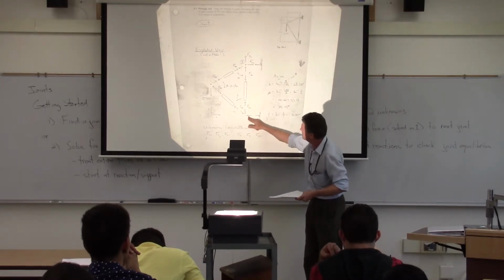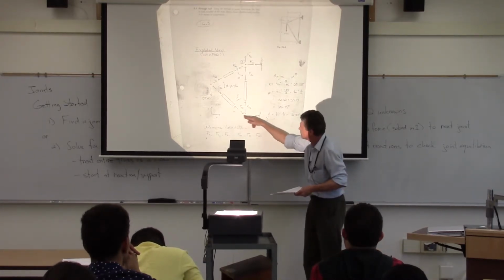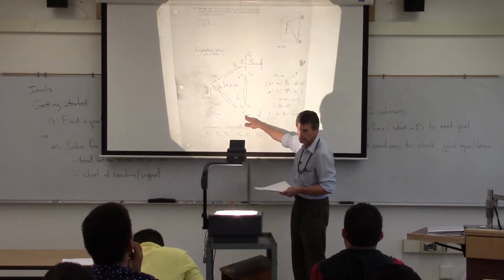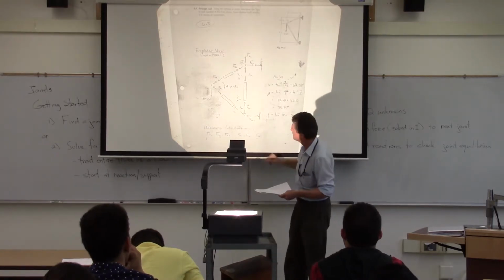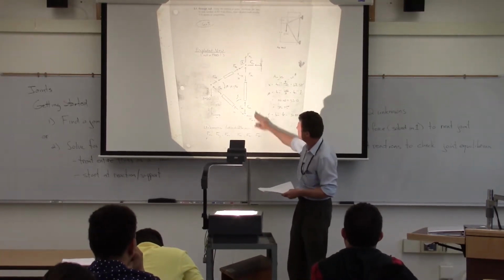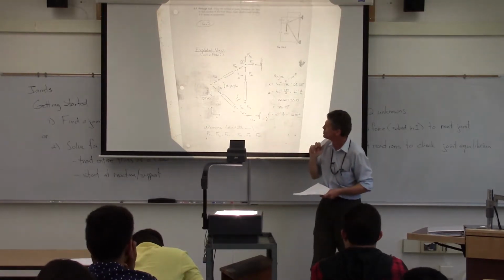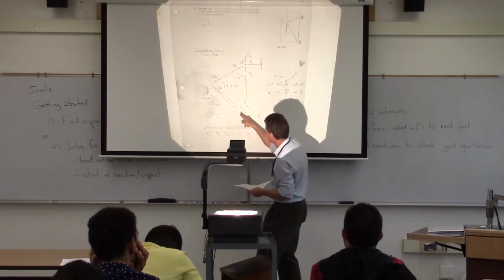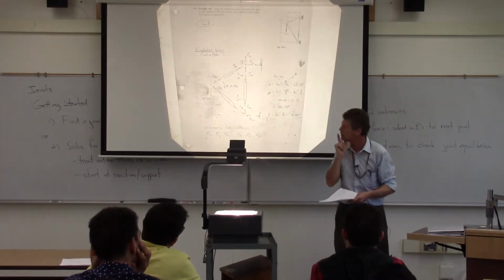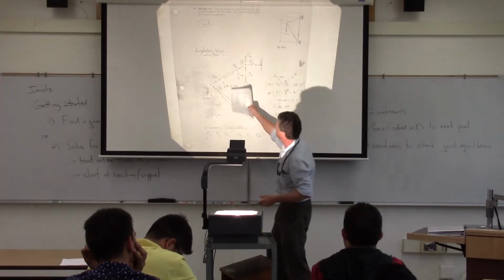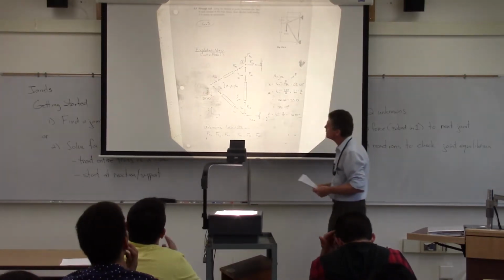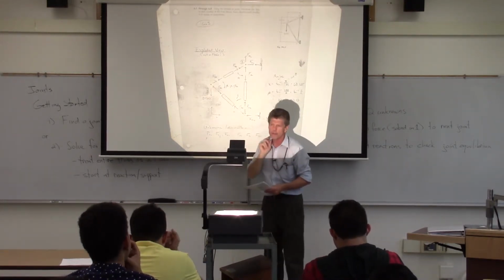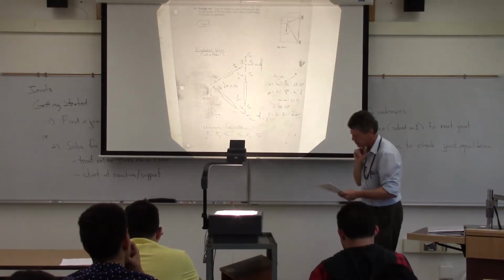Again, we've got a roller support here. So the ground sees this, the ground's pushing back on our structure there, but it's pushing at that joint. So we're going to have a component of force at that joint there, and we're going to have a component of that force there from FAC, and then when we look at FAB, we're assuming that particular member's in compression also, squishing the member there. If it's doing that to that member, then it's going to be pushing down on that joint like so. And then finally, out here at B, we've got the known load of 84 kilonewtons. Again, it's acting at the joint, as are the two member forces there.